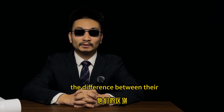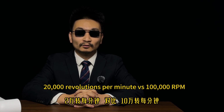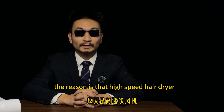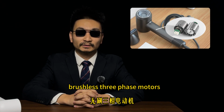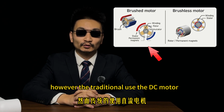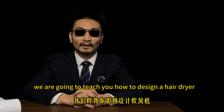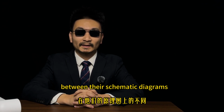The difference between their rotational speed is significant: 20,000 revolutions per minute versus 100,000 RPM, resulting in very different airflow experience. The reason is that high-speed hair dryers are equipped with more advanced, complex brushless three-phase motors. However, the traditional one uses a DC motor. Today, we are going to teach you how to design a hair dryer. First, we will show you the difference between their schematic diagrams.